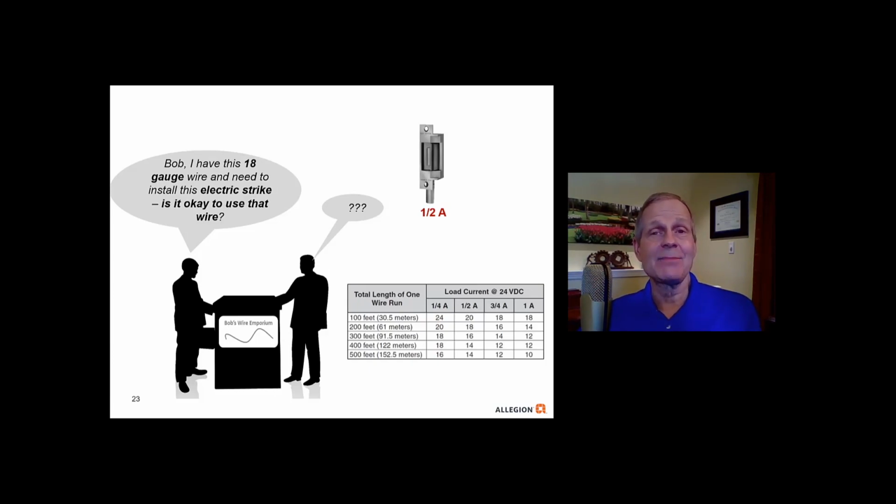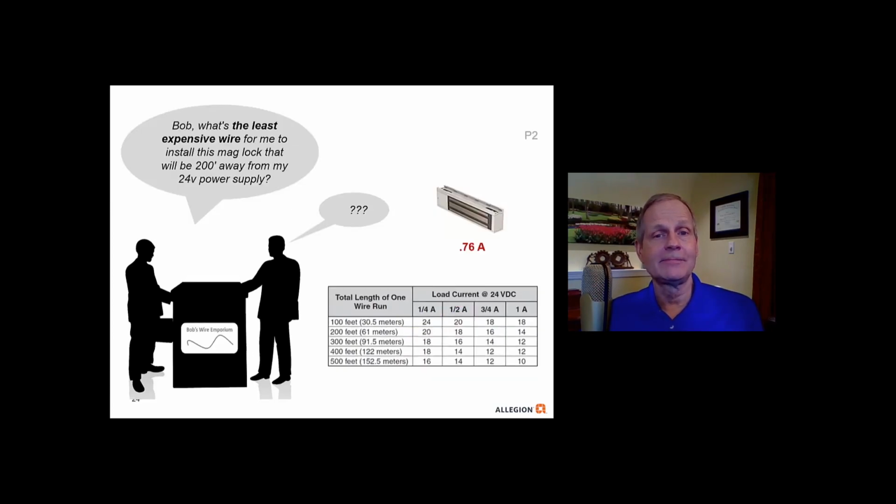And one of the missing pieces of this puzzle is, what is the distance between the device and the power supply? We need to know that in order to answer the question, can I use this 18 gauge wire? All right, so if it's 0.5 amp and 18 gauge wire is on hand, you could use it if you have 200 feet or less in your wire run. So that's how we could answer that. We need a little bit more information before we could tell the technician that yes, you can use the 18 gauge wire. The technician could use it in certain situations and not in others. It all depends on the length of the wire run.